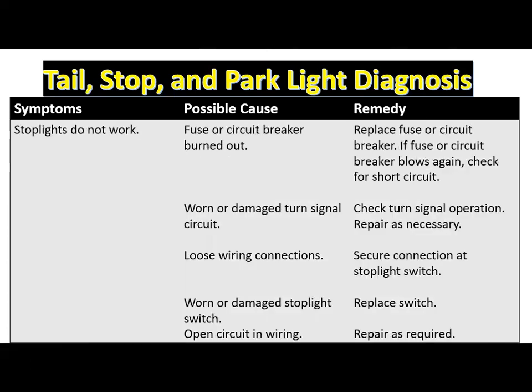Another symptom: stoplights do not work. It could be a fuse or circuit breaker burnout. Just replace the fuse or circuit breaker. If the fuse or circuit breaker blows again, check for a short circuit. You have to find it in the electrical system and trace it, using a circuit tester, an ohmmeter, or a volt multimeter, something like that.